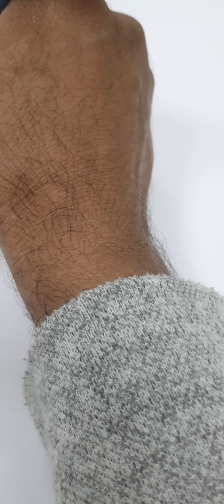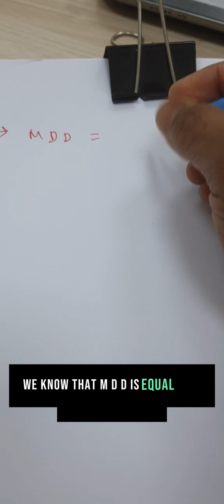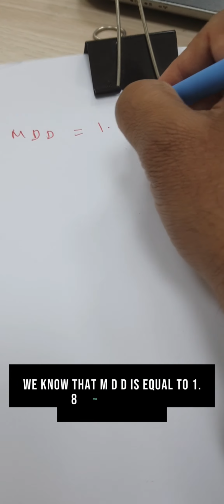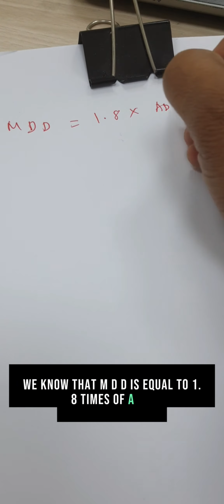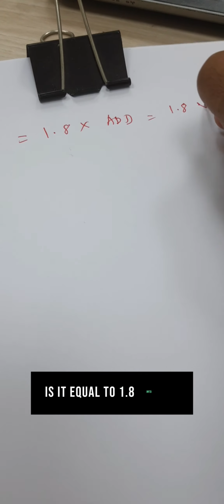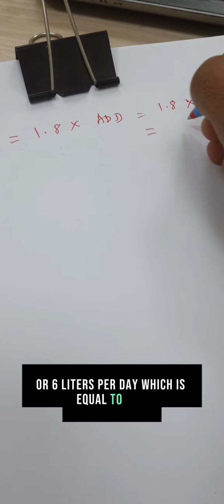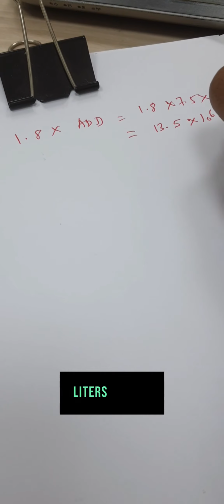After that, we know that MDD is equal to 1.8 times ADD from our previous units. So it is 1.8 into 7.5 into 10 to the power 6 liters per day, which is equal to 13.5 into 10 to the power 6 liters per day.